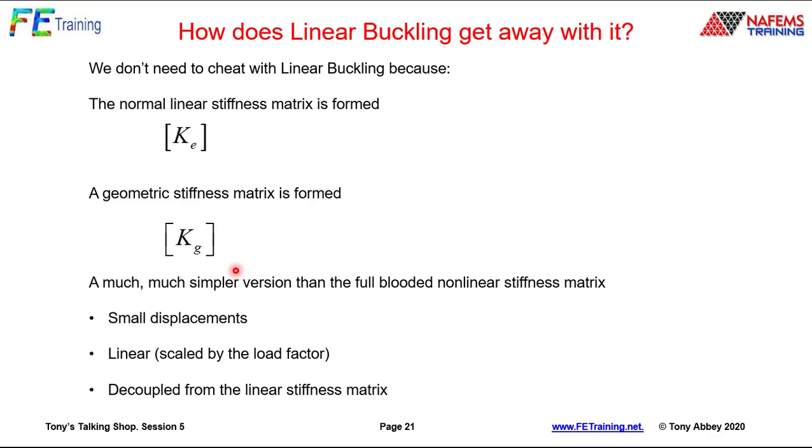There are some strict limitations on that. We're assuming small displacement theory. It's linear because it's going to be scaled by a load factor. So whatever value we get here, as we increase the load, it just scales up, which again is not the real true nonlinearity. It's also decoupled from the linear stiffness matrix. So it's a useful little matrix which we can develop, and we'll see how we do that in a second, but it's not the full-blooded kind of approach.